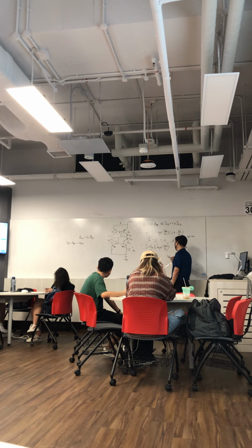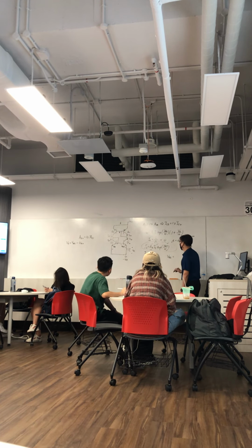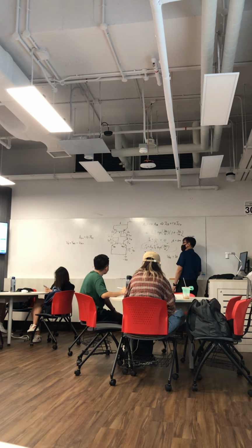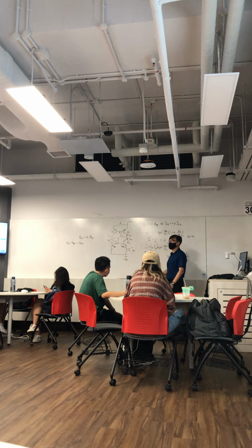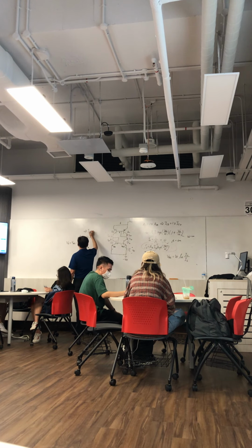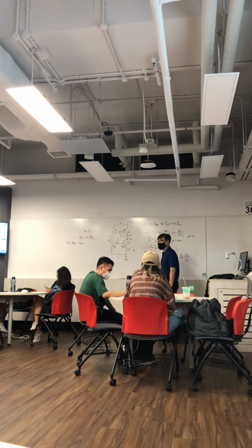If I express VBE in terms of IC, it's basically VT log IC over IS. Okay, IS means this whole thing. So when I say this is 10 times this, basically it's the same as saying that my IS2 is 10 times IS1. Your IS4 is the same. Okay? So if I want to simplify it, I write them together as IS.